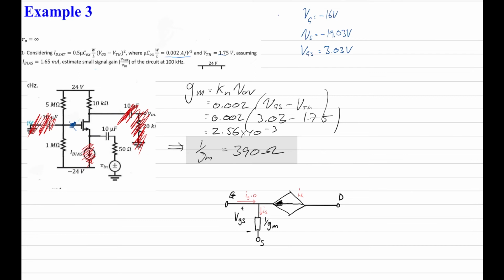And just to go over the reason for that, if we say the impedance of a capacitor is 1 over j omega c, if the frequency is very, very high, then this is going to be very low, i.e. tending towards a short circuit. So you can assume that those are actually going to be short circuits. And another thing at high frequency as well is that these current sources will be effectively open circuit, or they'll go to ground.